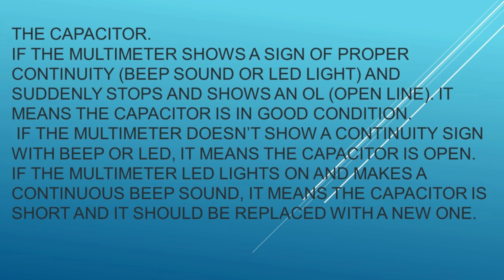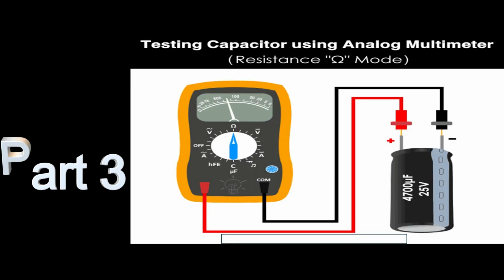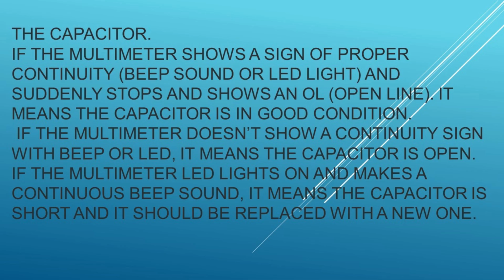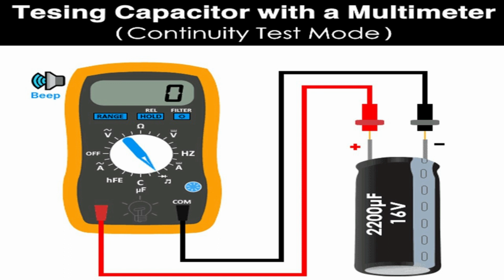For instance, if the supply voltage is 9 V, then 63.2% of the supply voltage is around 5.7 V. We will use a stopwatch and charge the capacitor until the value reaches 5.7 V. Stop the watch and note the reading of time in seconds. For more details, check the example given below the instructions.